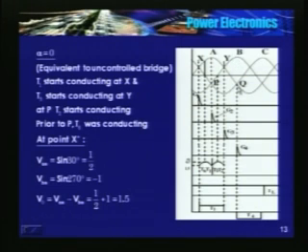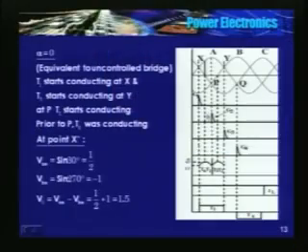And at point Q, phase A becoming more negative, the device connected to phase A in the lower half, that is 4, is triggered. So you will find this is a sequence 1, 2, 3, 4. That's why I have numbered the upper half as 1, 3, 5, and the lower as 4, 6, 2.